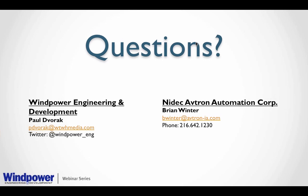Very good question. There's two kinds of EMI that can affect encoders and magnetic ones, but I'll go through both of them. The first kind is external magnetic fields, the M in magnetic, and that is brakes and other devices, the motors, generators that generate magnetic fields. And so what manufacturers do is they pick a combination. For instance, Avtron picks a combination of sensors that are angle sensors rather than magnitude sensors. So external fields can be readily ignored because they come from the wrong direction than the rotor. We can tell the difference between the rotor and the world outside. The second thing on magnetics is that most manufacturers who do magnetic encoders provide some forms of shielding. It's similar to an electrical idea, but you're routing the magnetism from external fields around the encoder. So in that example that we saw where the encoder was sandwiched between the motor and the brake, you're shielded from those powerful magnetic fields coming off the brake.